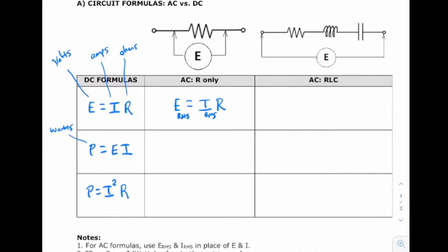So remember, the waves are going something like this, and then the RMS current would be about this, right? So here's 0, here's this, so this is called your peak current, and your RMS current happens just about halfway to the peak, right there. 0.707 times the peak. Remember this stuff? The RMS is 0.707 times the I peak.